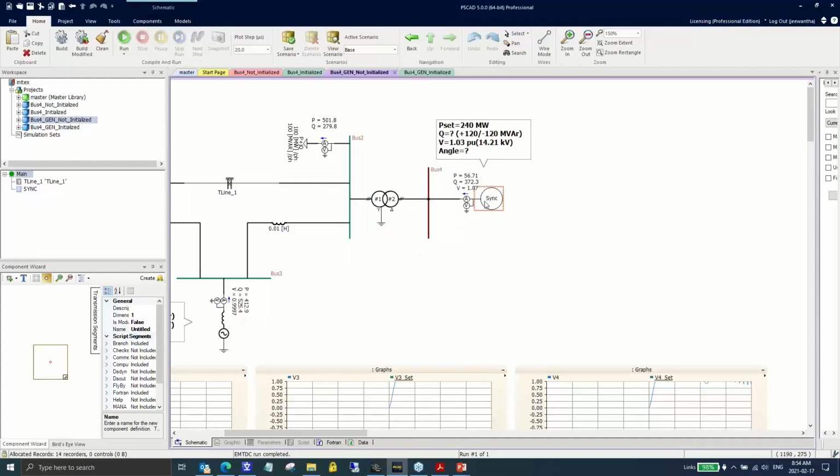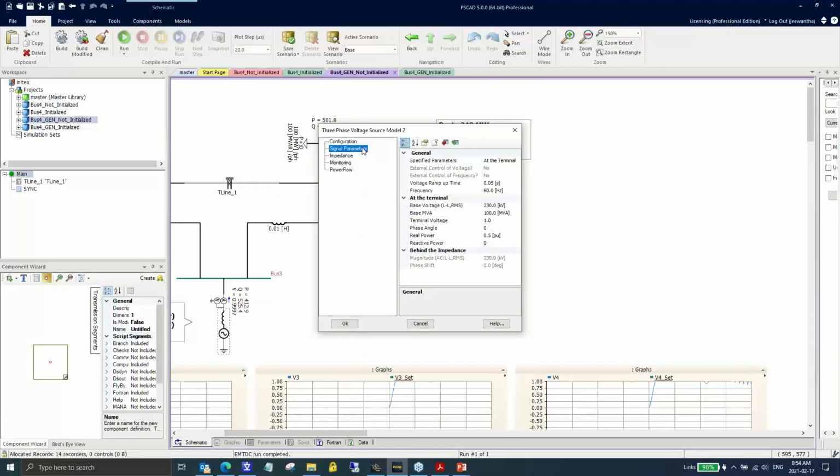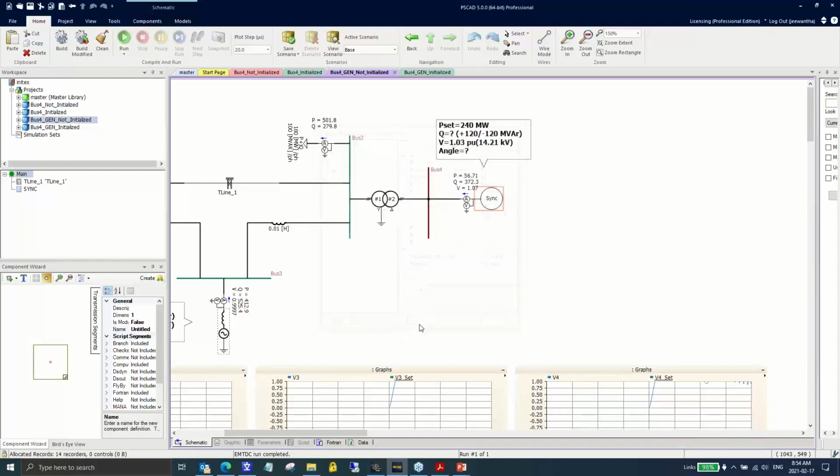The specific power flow that you want this to initialize to is provided inside either the generator model or the source model. If I go to this source model, the fact that you want this to be set to 50 megawatts or 0.5, you define it here. You just don't know the angle that would ensure that 50 megawatts come out of it. So the initial conditions, the operating conditions, so to speak, the dispatch levels are defined by you in the source model or the generator model, or in the case of wind farms, in the wind farm page module.